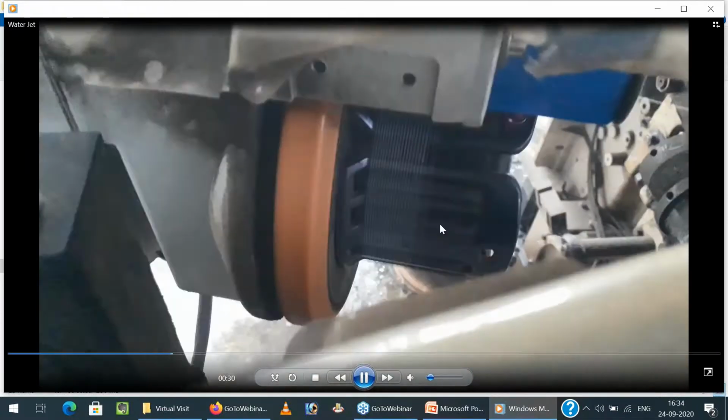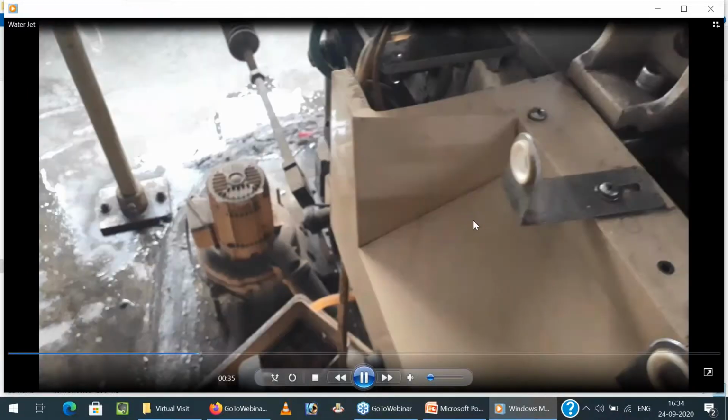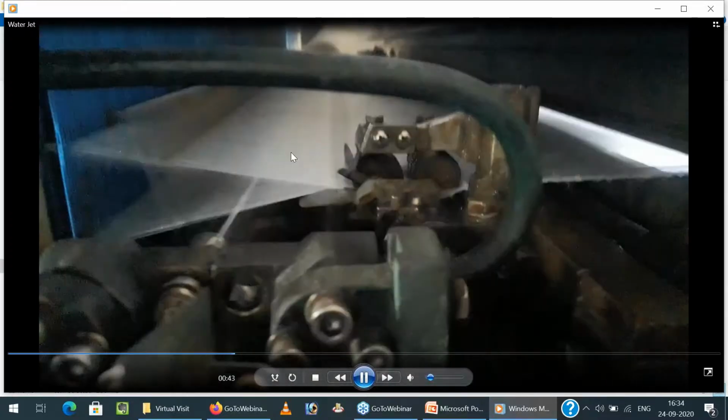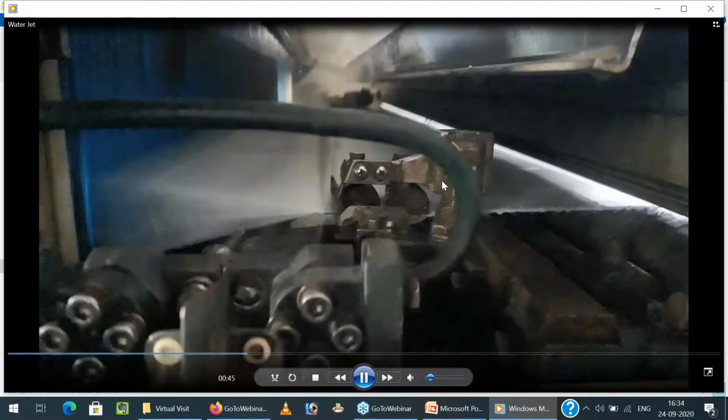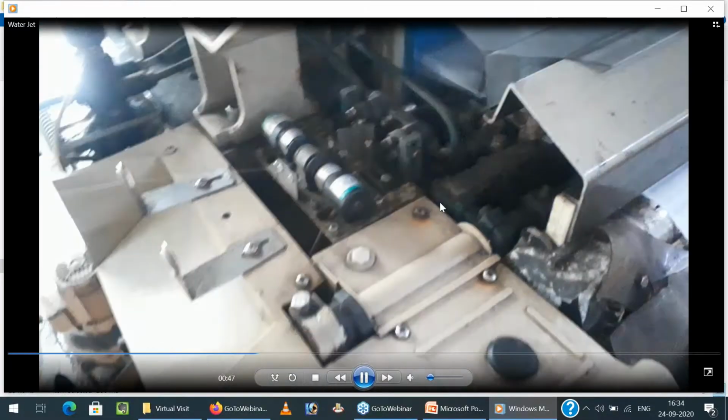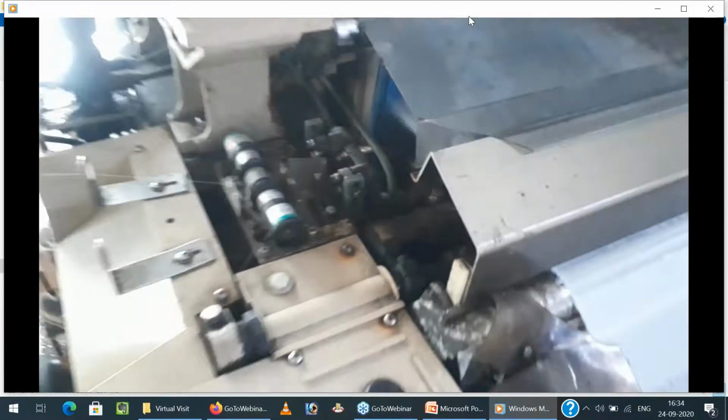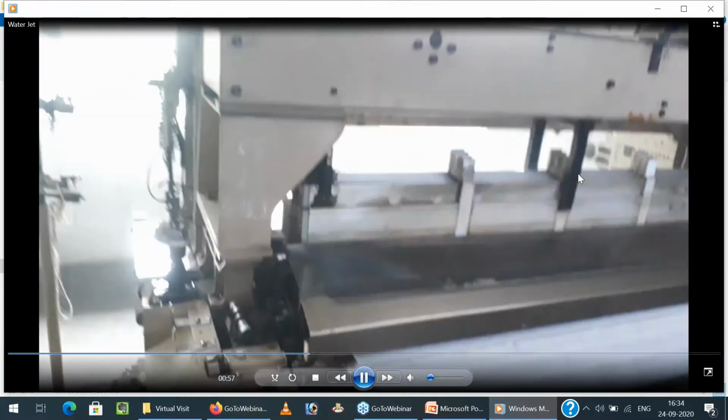And yes, this is particularly for synthetic yarn, which is mainly hydrophobic in nature. The weight is very light. It is not mainly used for cotton. And the previous one, which is air jet, is used for slightly heavier yarn, say coarser count, mainly used for cotton, mainly for making denim fabric. The heald shaft system and the other systems are all almost similar.